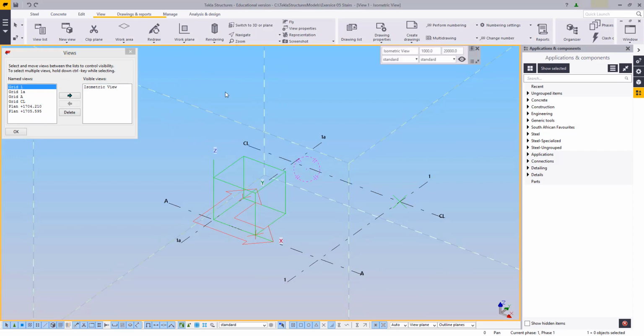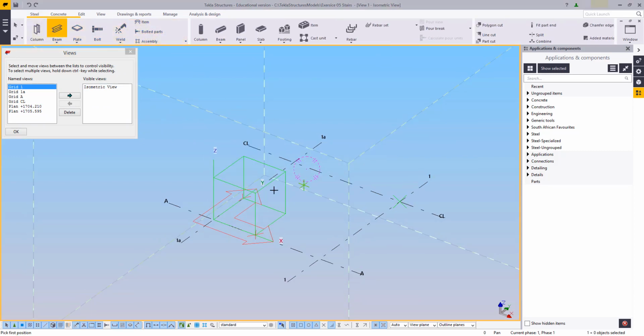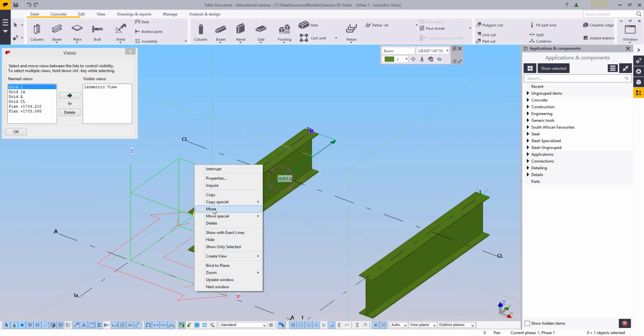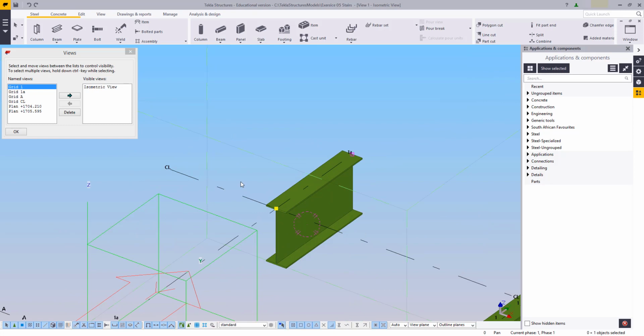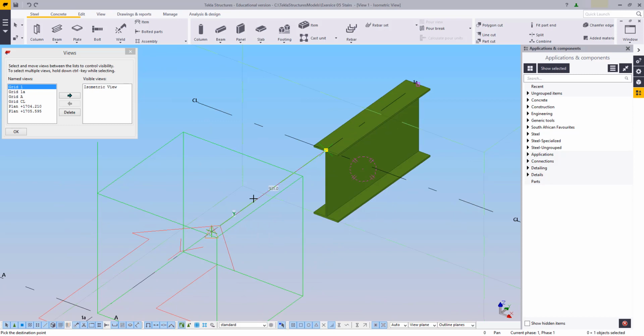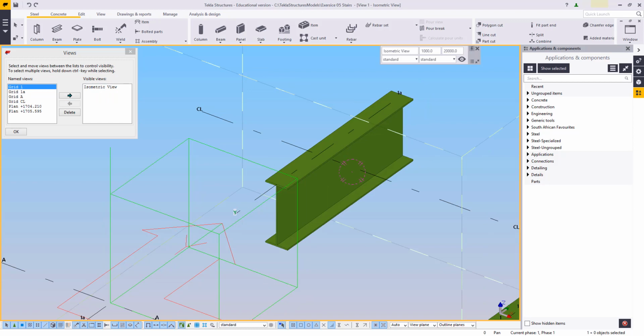Besides the center line, we are going to put in a beam, and this beam will be relatively from somewhere over here to that side. Same with this one. I'm just going to put a line through. Now for the bottom one, I don't really care that much up to where it goes. For this one over here, I'm going to move that to the center, and then I'm going to move it 375 in, and that should look roughly the same as the drawing we are working from.